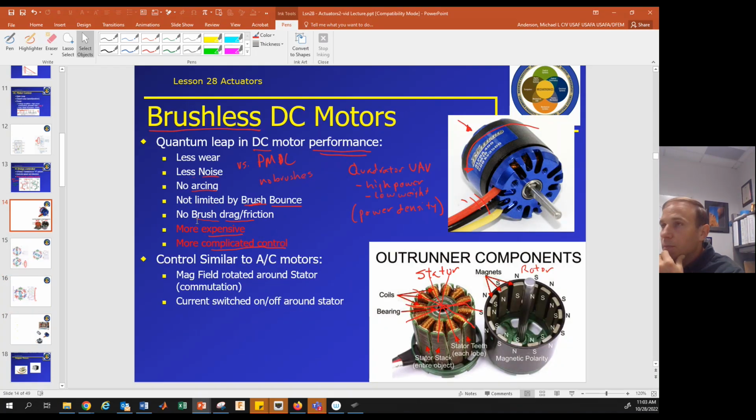So types of motors. Quickly again, a brushless motor is going to have less wear, be more efficient, and be lighter for the amount of torque that you can get. The drawbacks are that it's expensive and more complicated to control. You need a separate controller, or a microcontroller that is programmed to be able to turn the motor on and off.